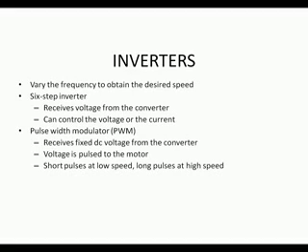The rectifier comes in 2 types. Phase-controlled rectifier, which converts AC to DC power. It uses a silicon-controlled rectifier and transistors. The capacitors smooth out the DC voltage. The other one is called a diode bridge rectifier. It does not regulate the DC voltage. Diodes are not controllable, and the voltage and frequency are adjusted at the inverter.